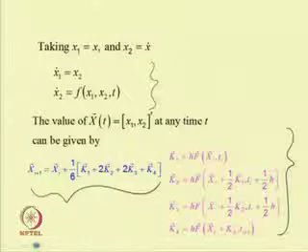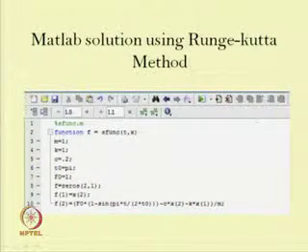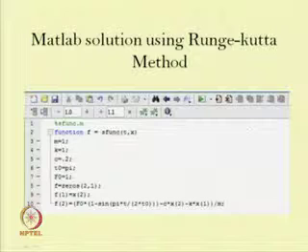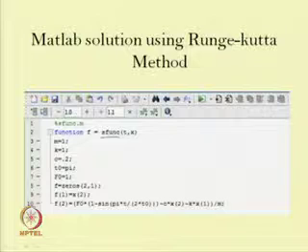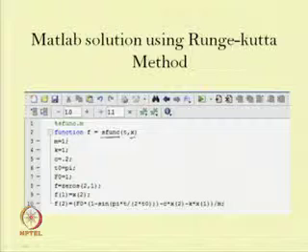So, for example, this is a MATLAB code written to find the solution of a single degree of freedom system without the nonlinear term. This is the function file. In this function file one has to write this function: f equal to, the file name one can put as sfunc. Here the inputs are t and x. Let us take m equal to 1, k equal to 1, c equal to 0.2, t0 equal to pi and f0 equal to 1.